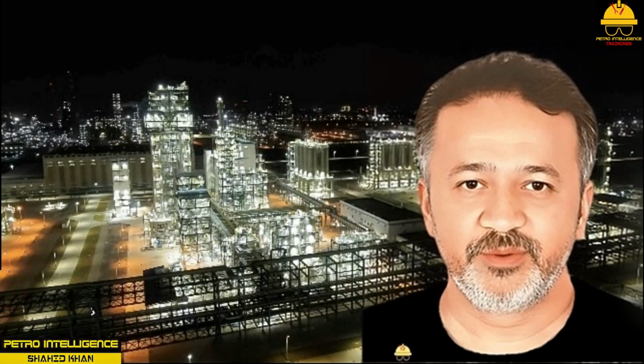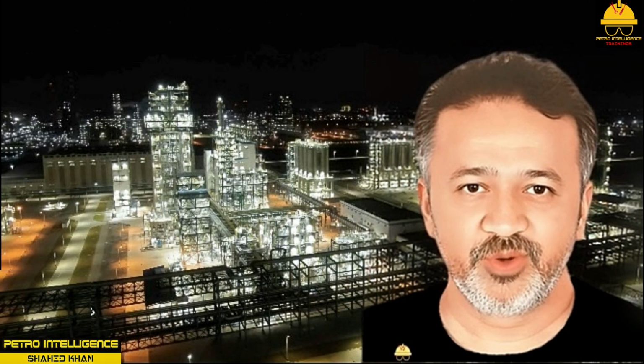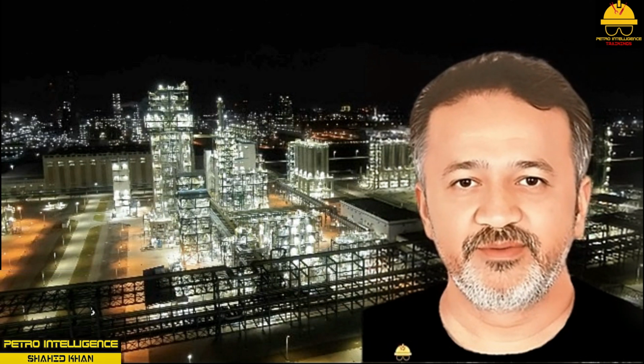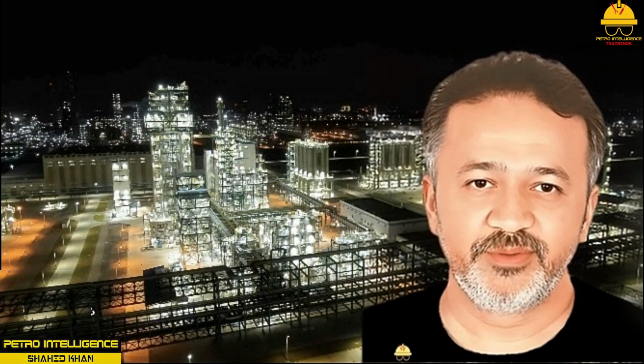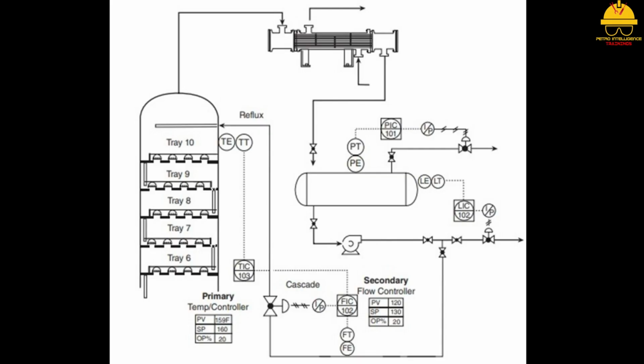Cascaded control loop. A cascaded control loop utilizes a series of unique features in modern process control. In a cascaded control loop, two different control variables work together to control a critical variable. For example, in some cases temperature control is more important than flow. In this case, a cascaded control loop can be used.